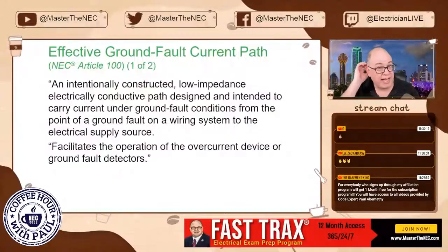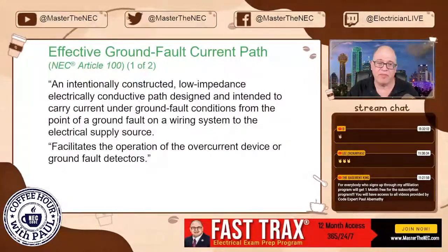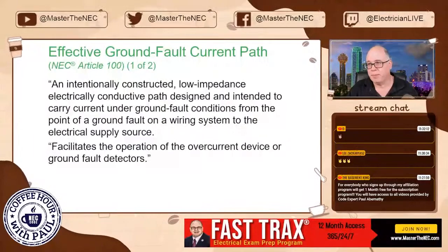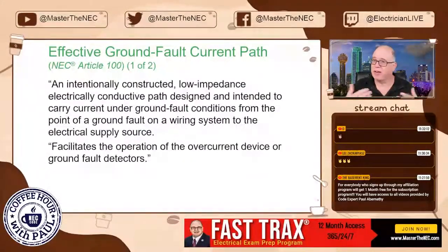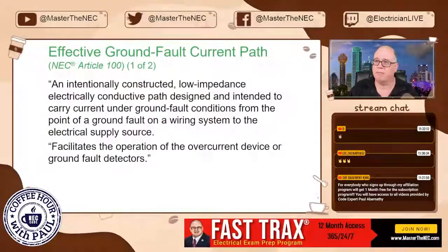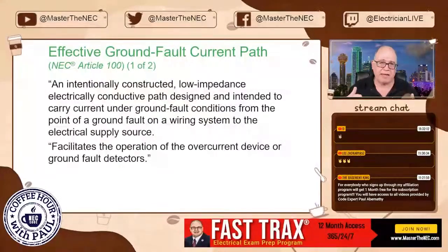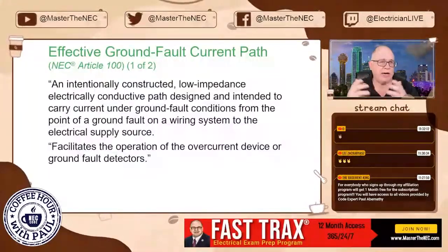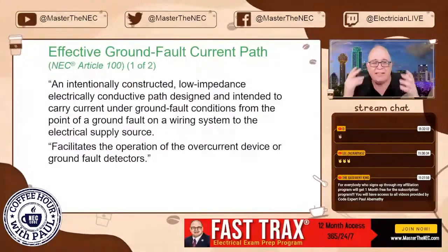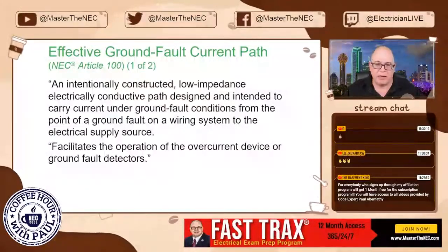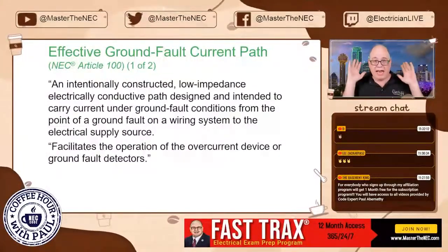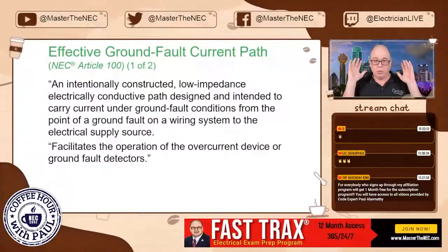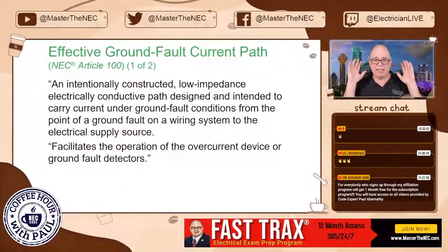Now, when another leg has a ground fault, then the system will clear. But an ungrounded system has a monitoring system, a detection system. There are many places, like smelting plants, which have a process that might be pouring molten metal. They can't have a breaker clear right away. So they want lights to come on. They want sirens to come on. They want to let everybody in the building go hands off. We want to put this in an electrically safe condition.